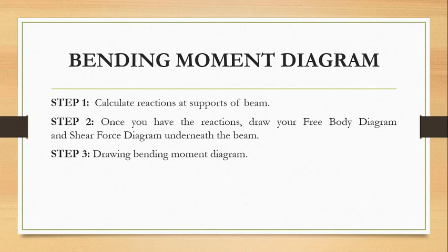In the bending moment diagram, we take the cross-sectional area of the beam and see whether the material is fully utilized near the support or not. So this is actually the insight of the beam to give us an idea whether that beam is going to be an efficient beam or an inefficient beam.